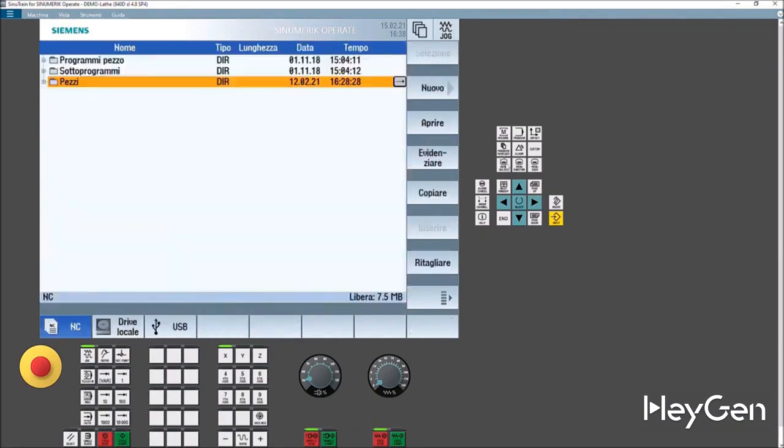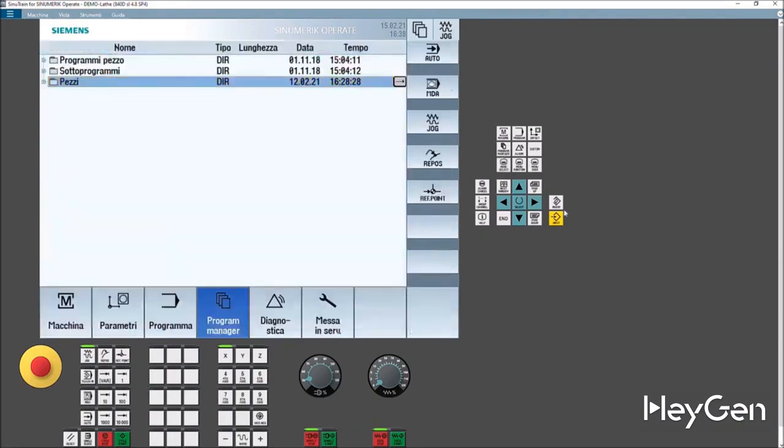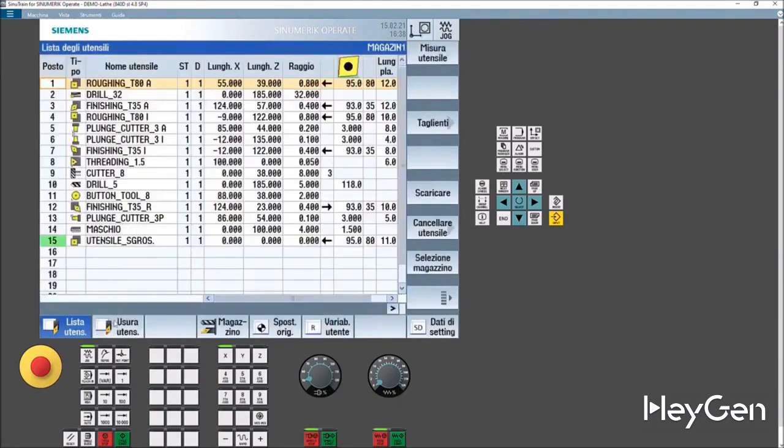So, the menu adds parameters to the tool list. Some standard tools are preloaded, and graphical images appear. It shows 80 degrees, the insert angle. The software is great for learning. Setting the insert angle to 55 auto-adjusts graphically. I set 80 and it displays a rhombic shape. Changing the tool holder moves the insert.